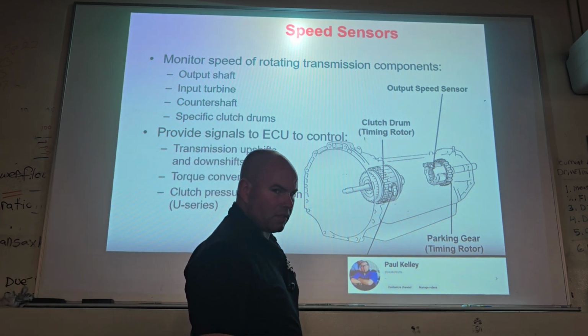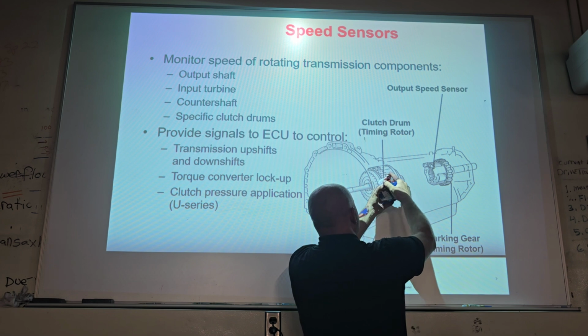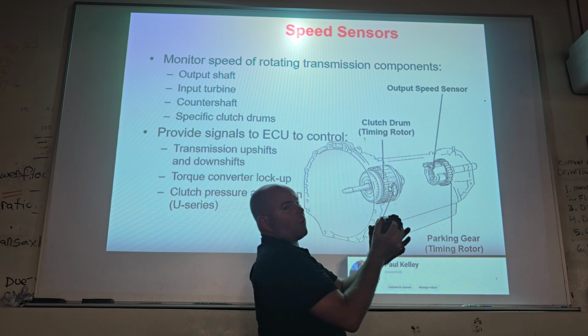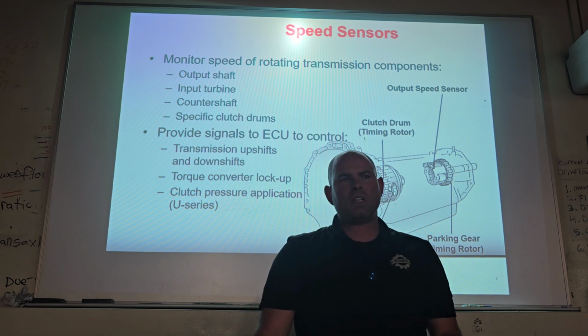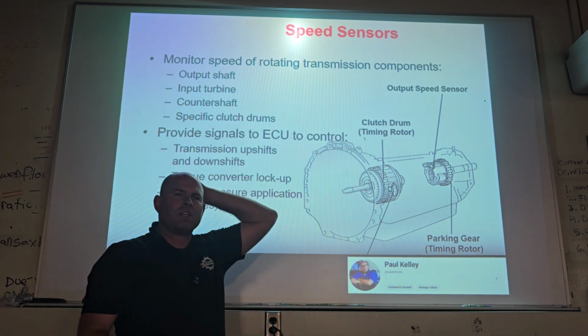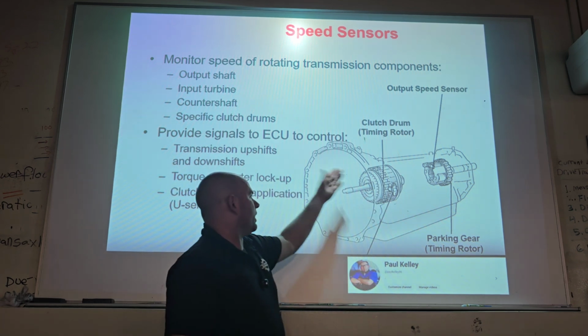Right? So it's going to use various gear sets like this. It's going to turn something, it's going to hold something, and something's going to be output, and it may do that 3 times or 4 times. If that's an 8-speed, it's got 4 planetary gear sets. And each one of those planetary gear sets, we have a clutch becoming the input, right? So like on this one,